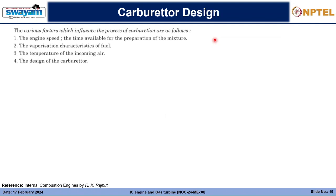So next we talk about the carburetor design. So there are various factors which influence the process of carburetors, which are as follows. So we talk about the engine speed, so the time available for preparation of the mixture, then the vaporization characteristics of fuel, temperature of the incoming air, and design of the carburetor.